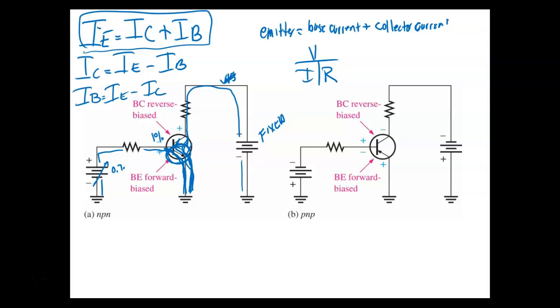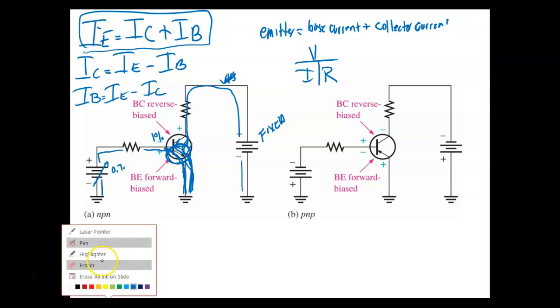And that's why the other ones are minus, right? You understand? So the other ones are always going to be, what's the smallest? What's the smallest current? The base is the smallest. The only difference between the emitter current and the collector current is that extremely small base current. Yeah, the base is always the smallest. That's where we get our gain. This is our valve right here. And this is what I showed you a while ago.